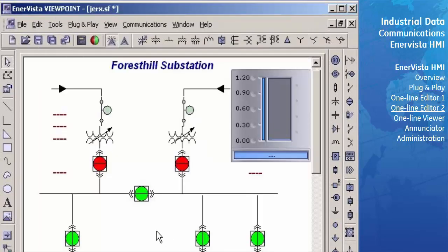We will now conduct a general test to see if our schema's monitored components are connected and configured properly. The system editor command we will be using is the one-shot test. The one-shot test is designed to perform a one-time poll of analog and digital values from actual devices that we have configured, and then to display those values on our schema in the system editor. It does not, however, validate whether or not our control components are set up properly. To check our control components, we'll have to use the system viewer.